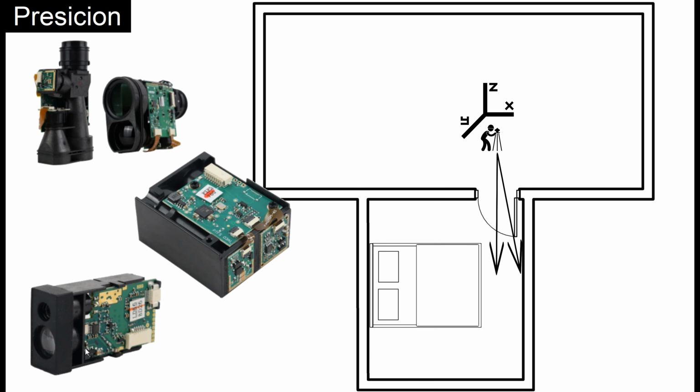I've actually been thinking about a solution for this issue, and maybe finding a laser sensor that can accurately measure long distances is the way to go. Unlike ultrasonic sensor, laser-based sensors are less affected by dust and provide more precise readings over greater distances.